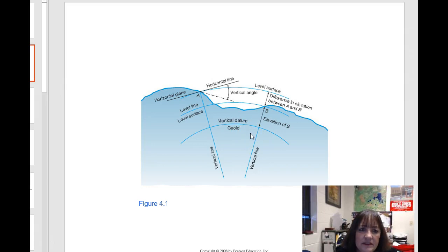And it's somewhere in the vicinity of sea level. So when you read something like the city of New Orleans is 8 feet below sea level, it really doesn't mean that there's a wall of water 8 feet tall off to the south of New Orleans. It just means that whatever this datum is, New Orleans is below it. And those numbers don't change.